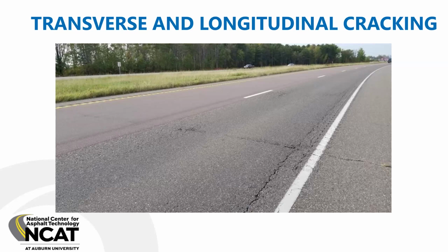is as wide as the driving lane, and that's so that combines and farm equipment have space to run while traffic is progressing out there in the truck lane and the passing lane. So that longitudinal crack that you see there inside the edge line stripe, that's actually a longitudinal joint that is coming apart. And again, you have a very aggressive environment. So if you get a little bit of a crack there and water gets in it and freezes, it can push that apart, just like it does with the thermal crack.